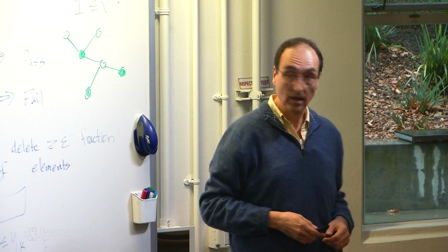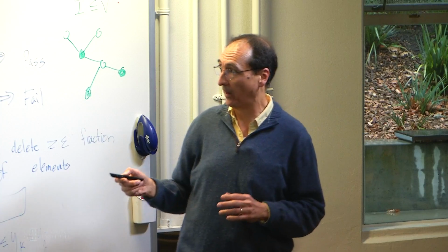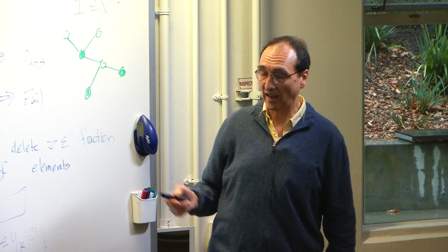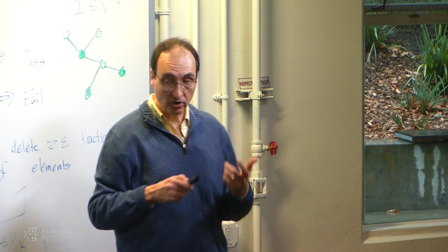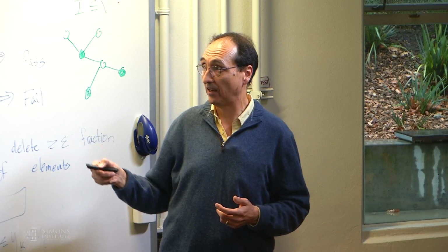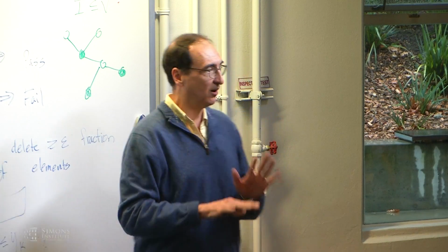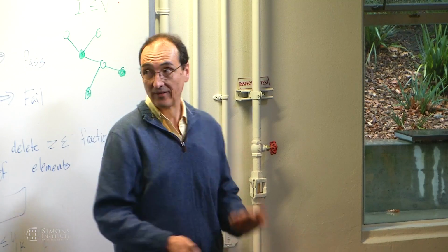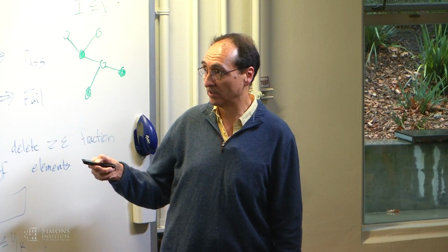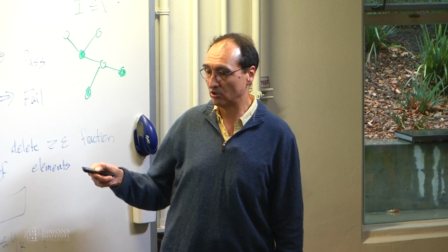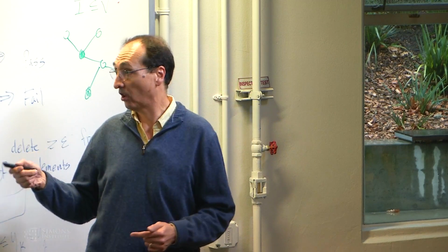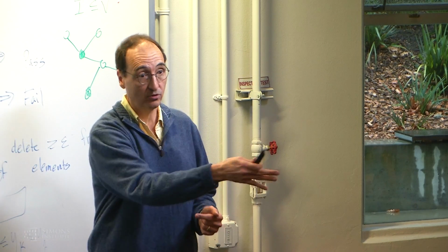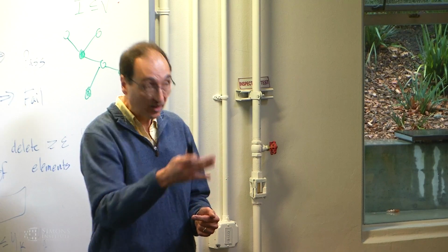All of that stuff. And so we think about that, for example, as when I create those layers, I have to have an understanding at this layer of the design, I want to treat the lower layers as just a simplified abstraction. And so I've got to have some contract that says, for example, the online optimization is going to assume that if I tell the lower level feedback control to track this trajectory within 10 centimeters, that it's going to do that.